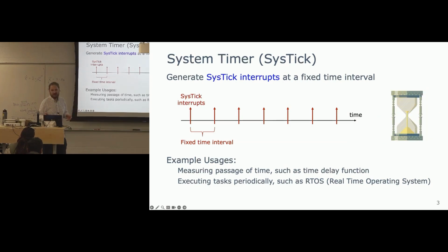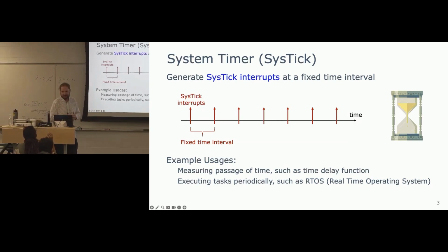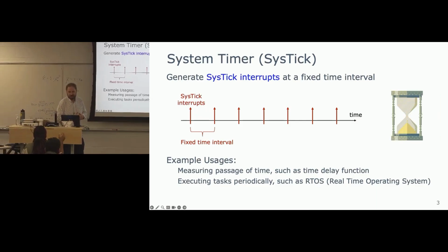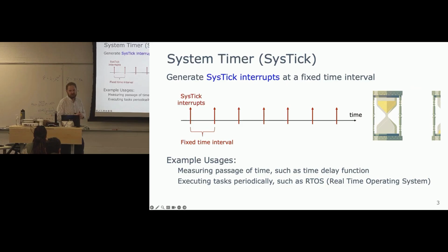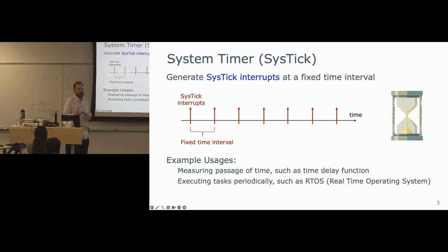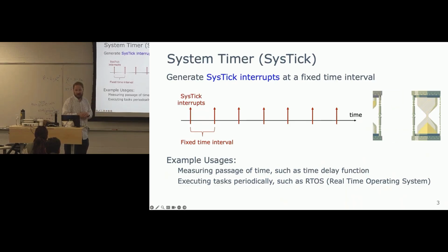All right, any other questions? Yeah. So is it sort of treating all the tasks as if they're interrupts and then moving between them? It's not treating the tasks as interrupts necessarily, but you're not writing them in the handler. You're saying interrupts control which task is going to go next, and when you're done doing the computation for a given task.